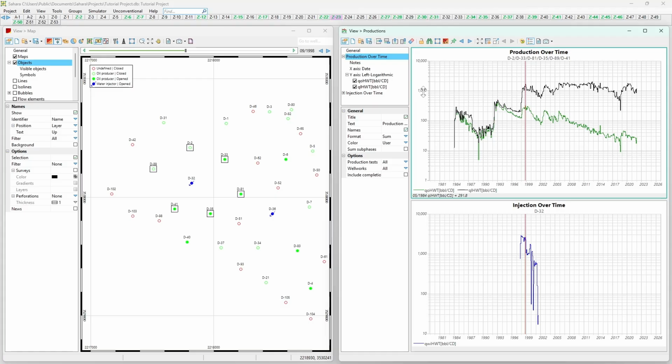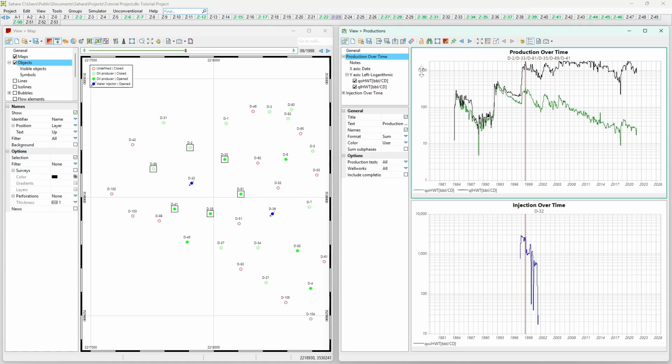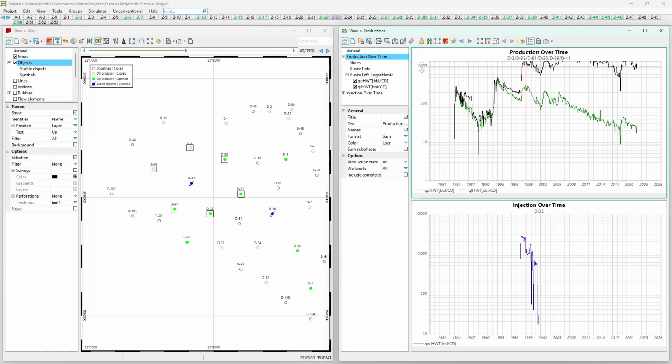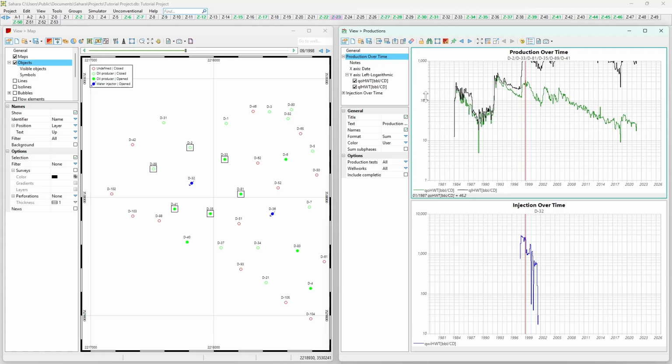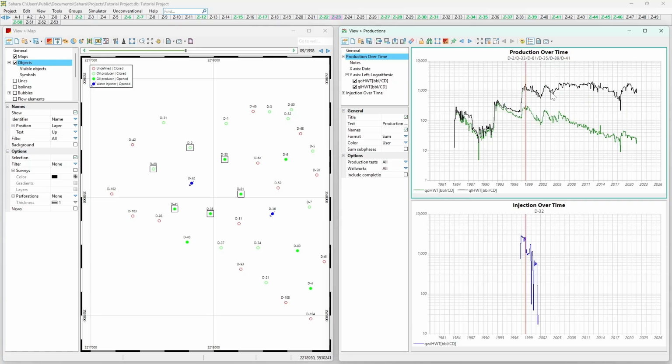And if I move it here, the value that is going to be considered in the logarithmic scale is always going to be a base 10 value, for example 10, 100, 1000. So in this case I'm going to plot up to 1000. And here if I double click on this y-axis, I'm going to have again the best fit with all the possible data that will be up to 10,000 for the logarithmic scale.